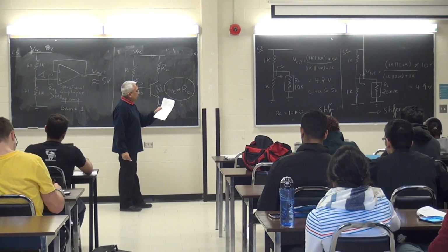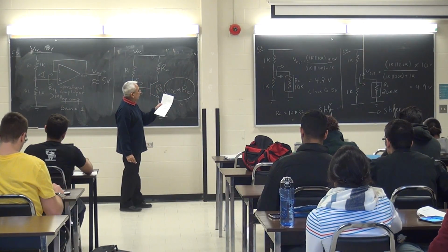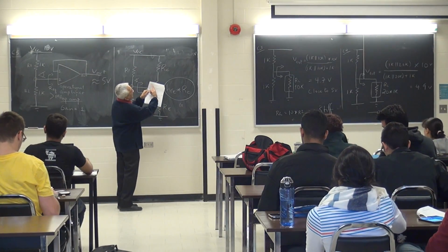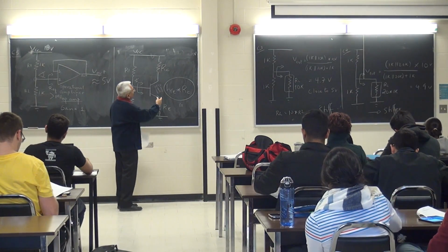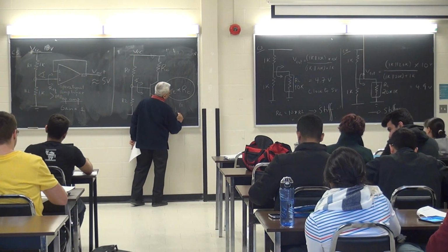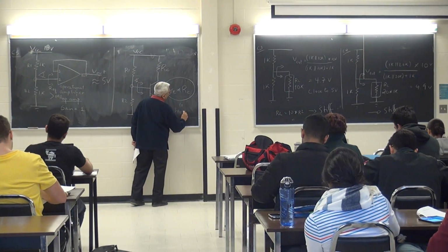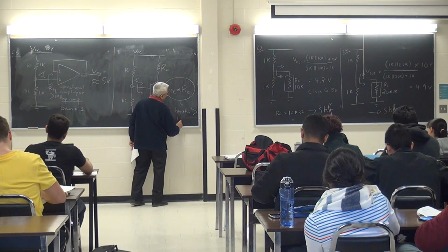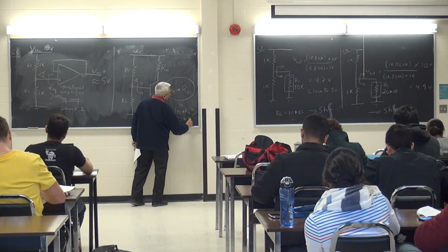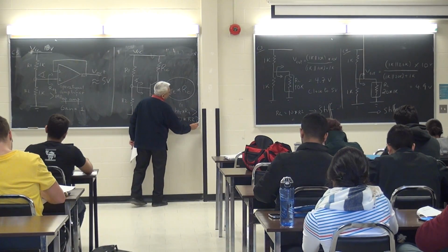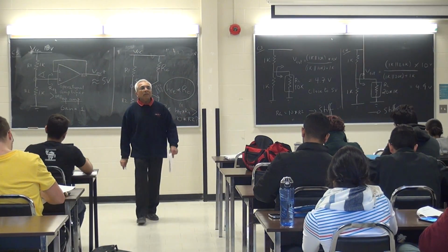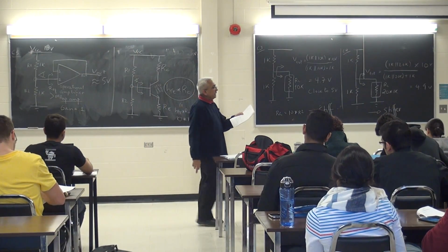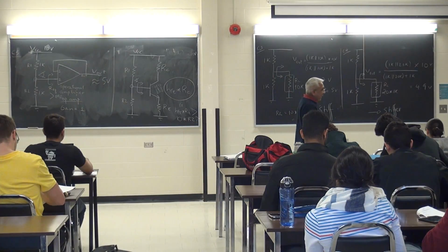Write this down, right beside the top line, at the top of page 2. Stiff voltage divider circuit analysis is HFE times RE greater than 10 times R2.